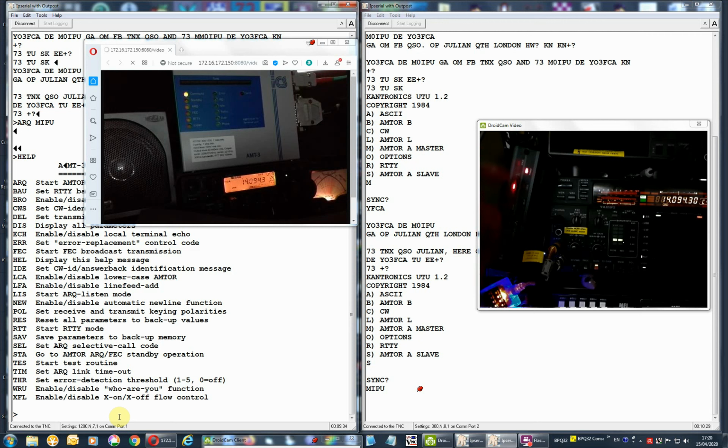You see LEDs flashing up on the bar graph there, either unit. That means the power source is very noisy. You should only see an LED when not in command mode, basically, as you can see on the right hand side, or as well on the AMT-3 unit here, you normally see one LED light up here, basically.